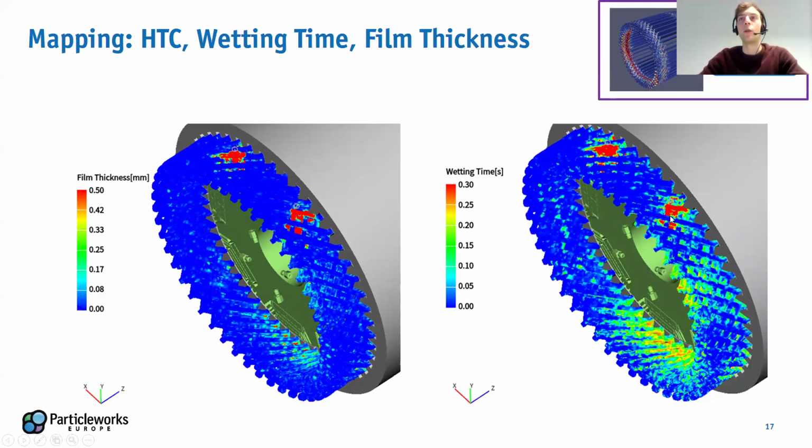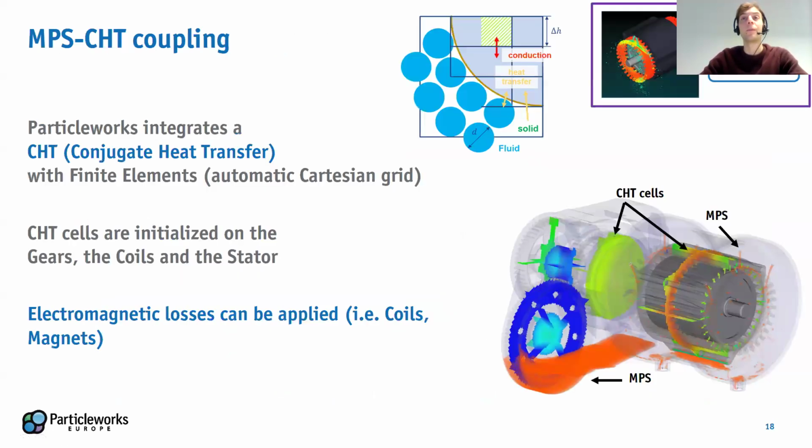You see oil flowing through the windings layers, and you can see accumulation and patterns of higher or smaller film thickness. So this is a very important feedback for designing or changing, let's say, the operating condition of the oil jets, or we can also look into how the oil properties can impact this kind of flow and impact the cooling capabilities ultimately. And then, as mentioned, these maps are applied to a thermal model.